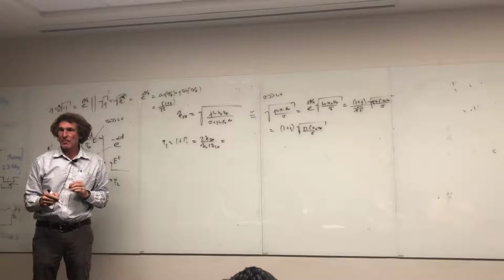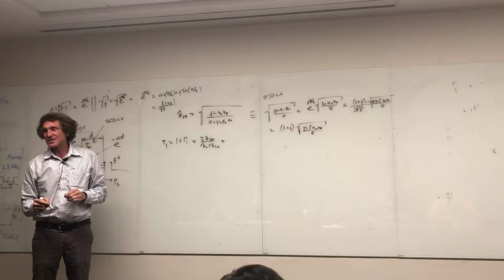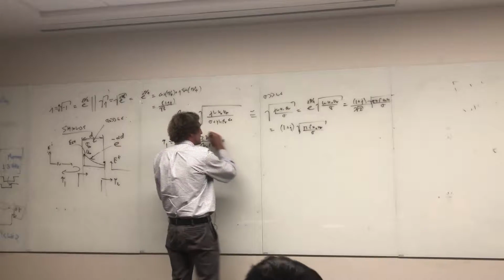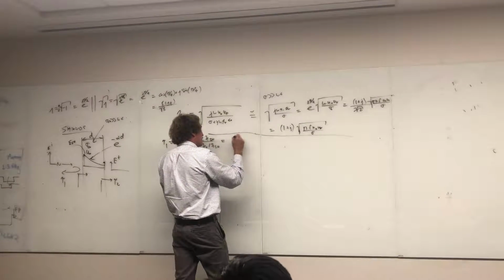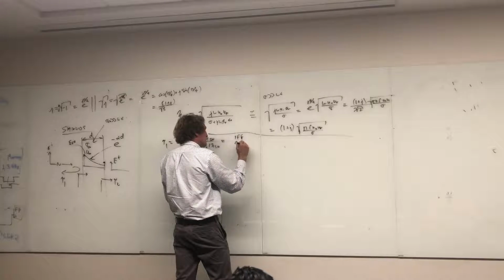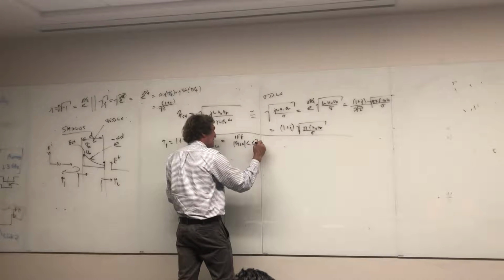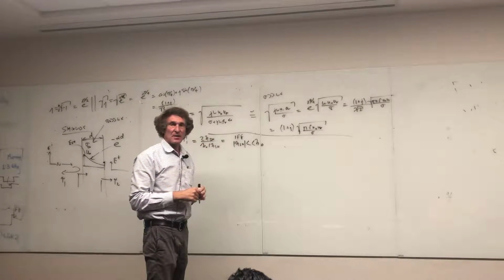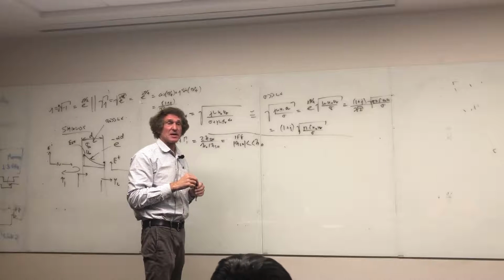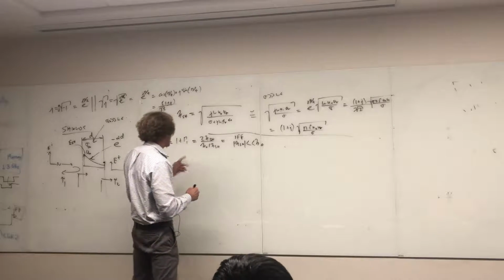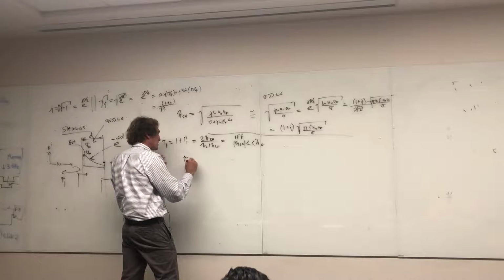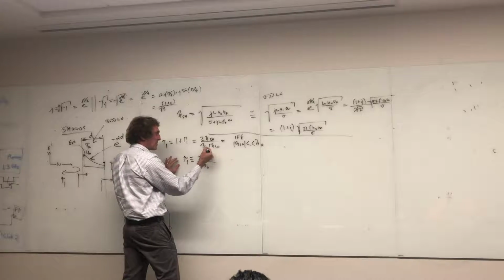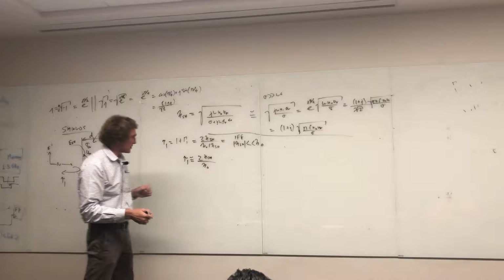Please watch this. This is important what I'm about to tell you. Now these are standard approximations that save you a lot of time. Write down: if, and only if, eta shield's magnitude is much less than eta naught. I know, more than an order of magnitude. If eta shield is, say, 2.5 at an angle of 30 degrees and eta naught is 125, that's much, much less. If that's the case, then we can say that tau 1, the transmission coefficient, is approximately 2 times eta shield over eta naught, because this number compared to that number is insignificant, and that's normally done. That's tau 1.